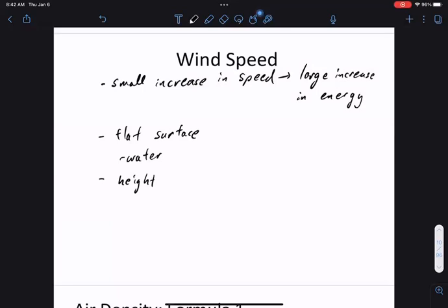Okay, so this comes from the fact that the friction is much lower. So you want to put it where it's flat, and you really want to build a turbine that's really tall. So you have higher elevation, you have higher speed. The best place to put it is a really big turbine offshore. That's sort of the best of both worlds. If you can't, then you go for higher ground, where you try to maximize the speed. Really, the goal is to maximize speed.